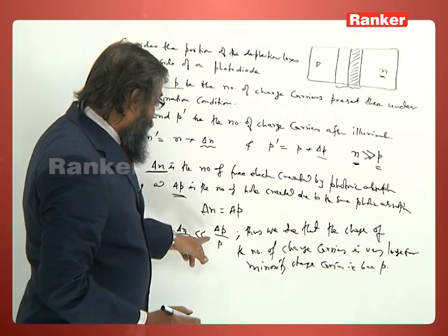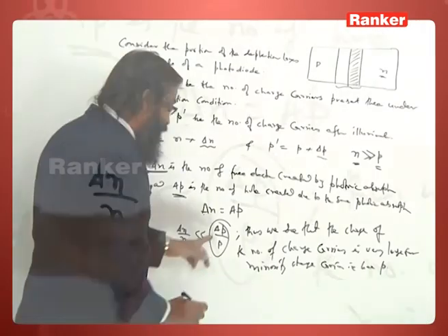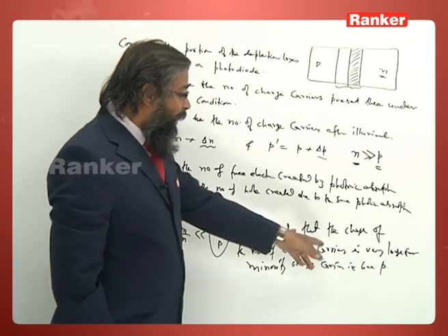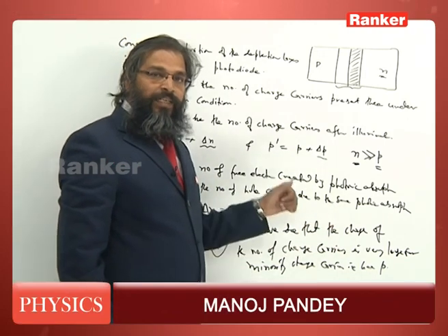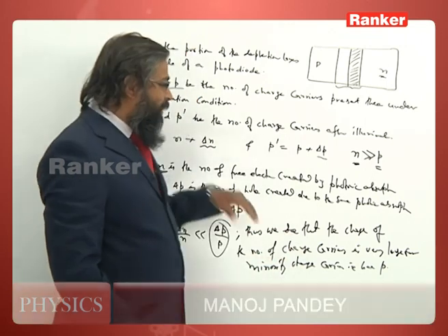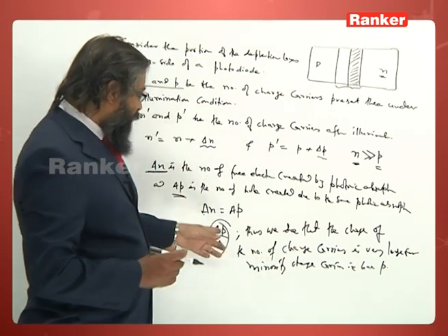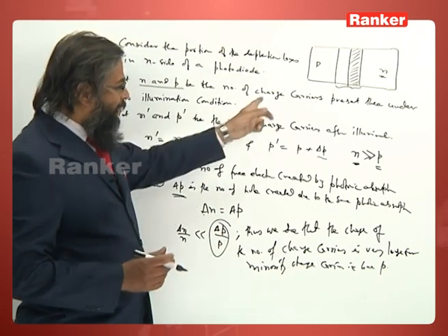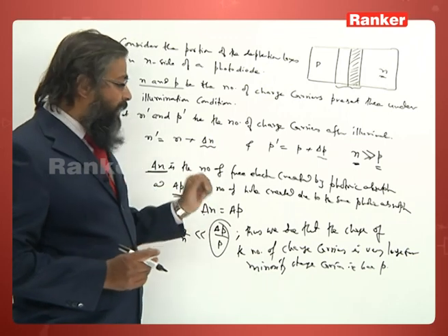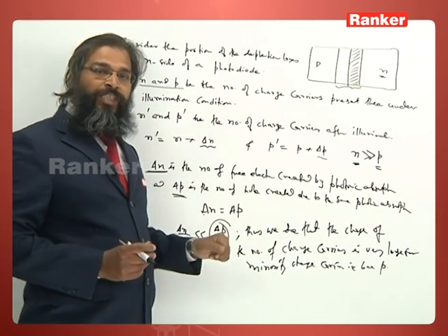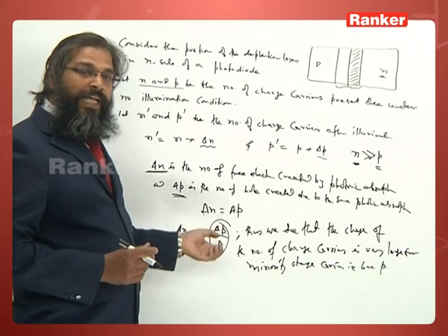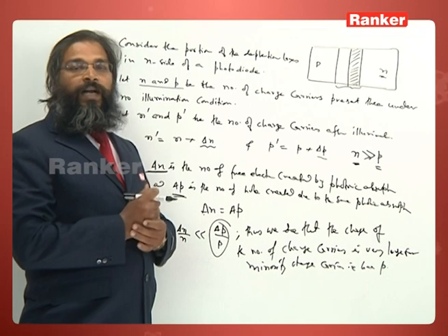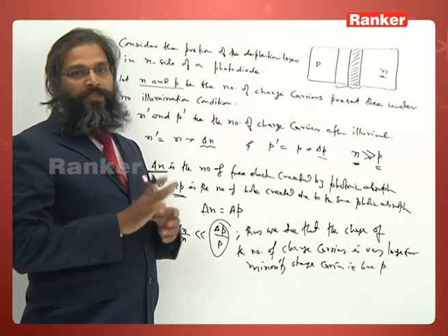So, here you see that this denotes the fractional change. The fractional change is very large for minority charge carriers. Now, that is what we have discussed in the previous article, that why it should be reverse biased. So, during reverse bias, the current conduction is due to the minority charge carriers, where a small change can be easily noticed. So, the photodiodes are always reverse connected.